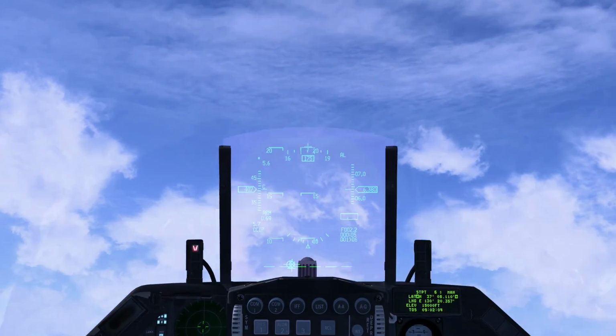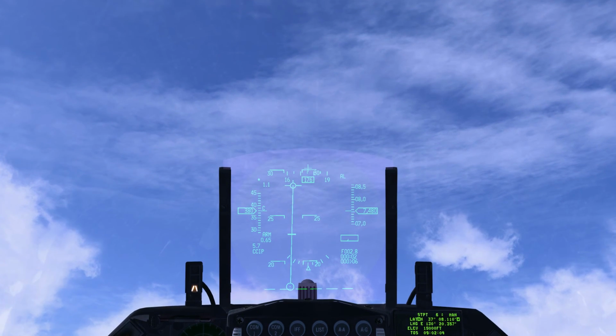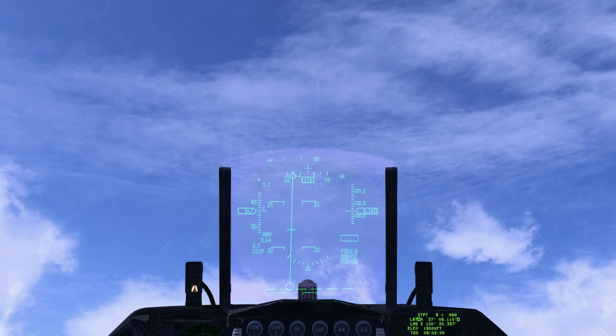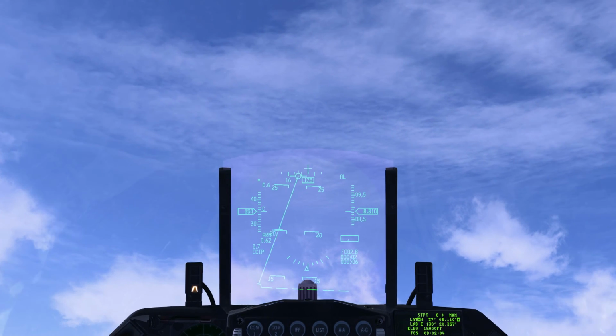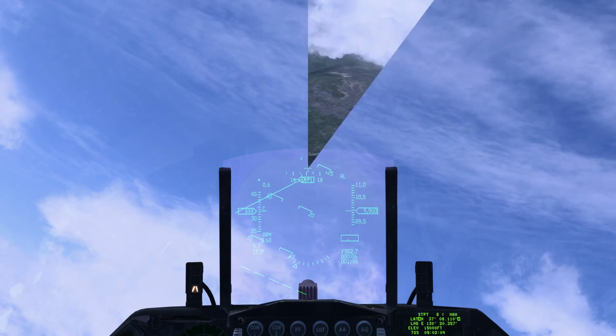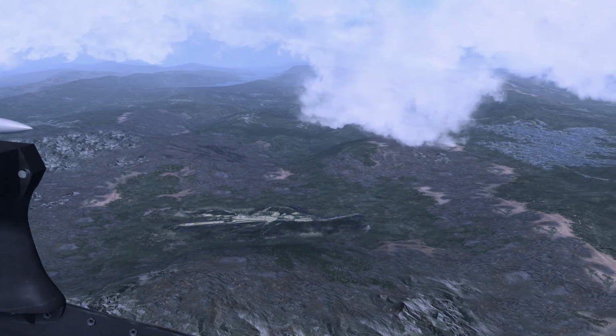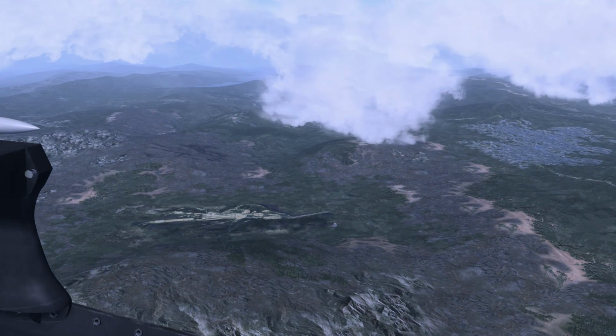The master caution light may illuminate after bomb release. This may indicate that the aircraft has gone from Cat 3 to Cat 1 loading. To clear the warning, select Cat 1 with the store's config switch situated on the landing gear panel. To return the hood to nav mode, press the A-A or air-to-air button on the ICP twice.